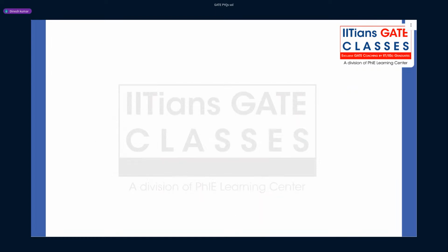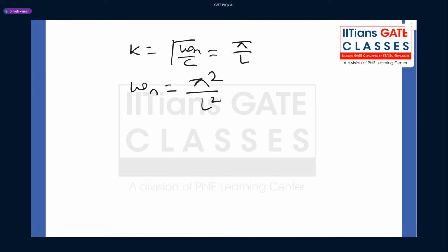And what is k in case of vibration of a beam? The k is given by √(ωn/c). This is a better way to write it. So here √(ωn/c) equals π/L. What is ωn? It is the natural frequency. So ωn will be π²c/L².